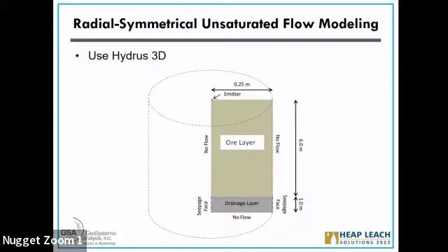And I come to the modeling. So we have established the criteria for the critical solution content, so we'll not try to hit that. Then we come down to the simulation. In here, we put the emitter here, and then we apply the solution through the emitter. In a 3D domain, we use HYDRUS 3D. This is about 6 meter depth and 25 centimeter in diameter to represent the usual spacing between the drippers.